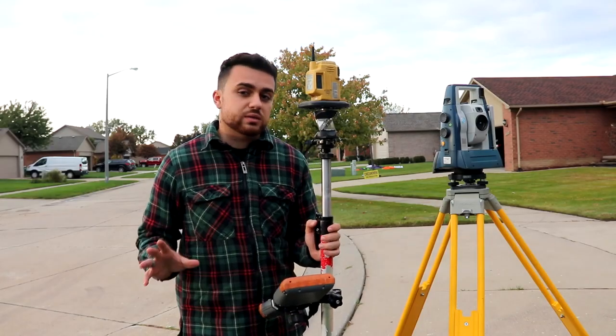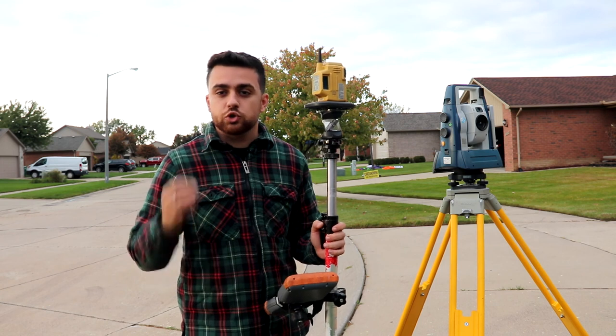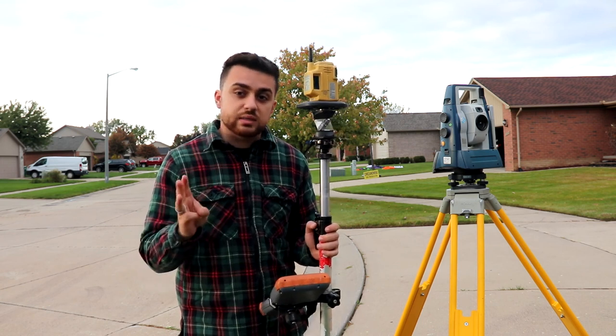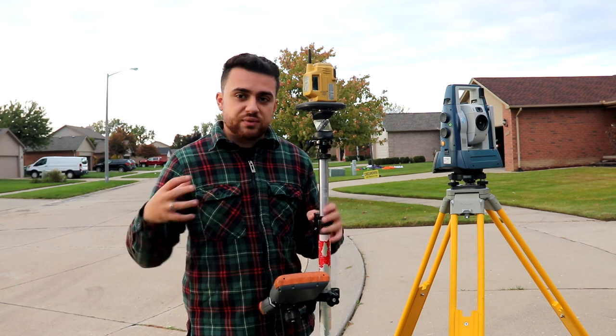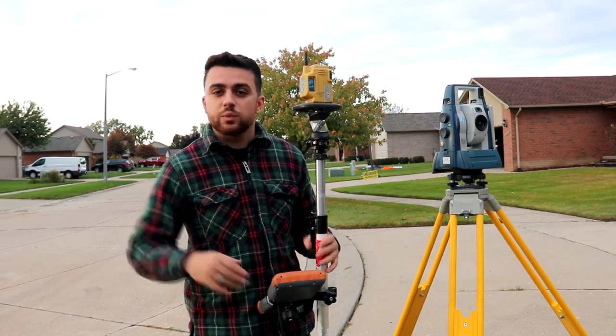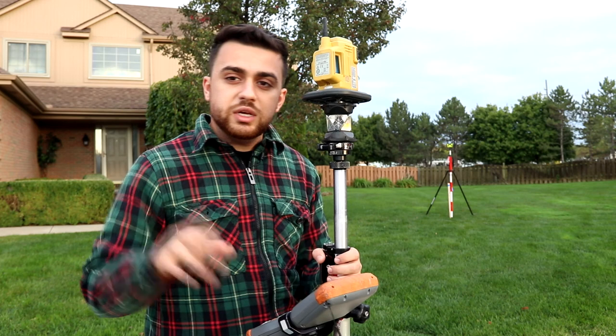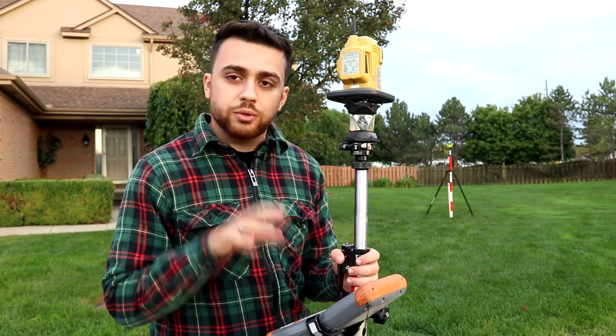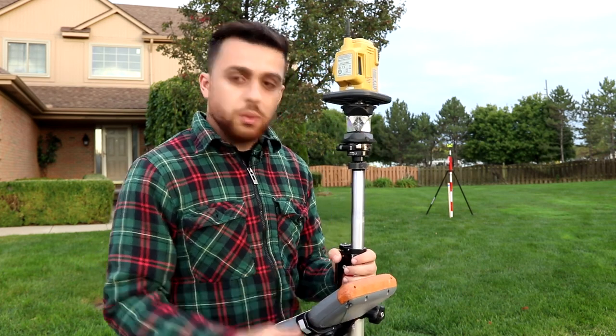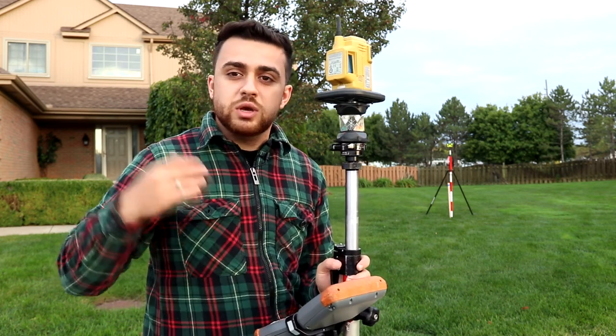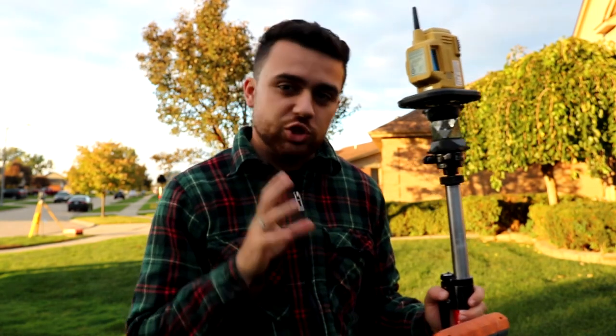Now this video is making the assumption that you have coordinates on your control points. That's X, Y, and Z. We're now establishing our control network and feeding that information into our data collector so that we can then survey off of it. I've already inputted the northings and eastings of both control point 1 and control point 2. What we're going to do now is tell the instruments where they are in relation to each other. Now I'm going to be using the Carlson data collection software. It doesn't matter what kind of software you use. It's all pretty much the same concept, same principles. So just follow along and figure out what kind of information I have to input.